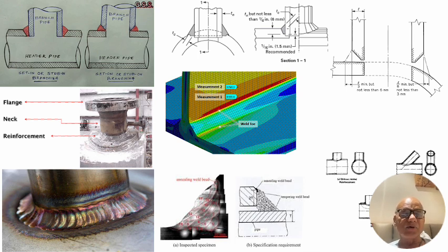And after weaving also, you are not sure whether you are going to get sufficient reinforcement on the fillet, otherwise there will be a recess as we saw in the earlier slide, and that may not qualify for the required throat length.